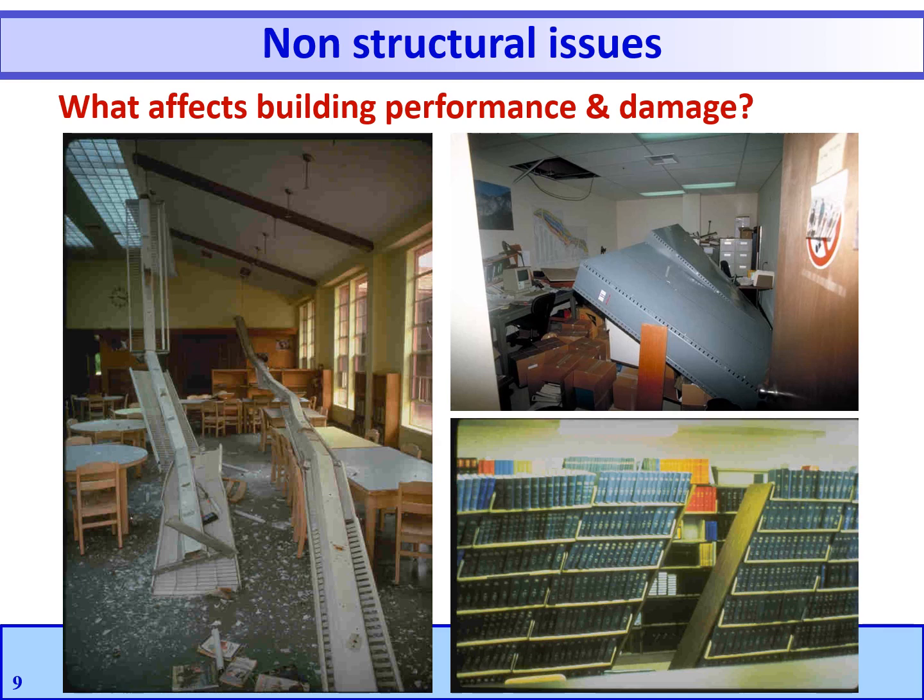Light fittings, cupboards, shelves, hanging ceiling parts can all modify the seismic hazard, most of the times unexpectedly. That is why detailing of installation and maintenance procedures, as well as compliance with product standards, are of paramount importance.